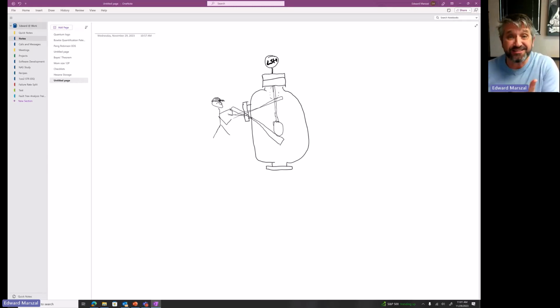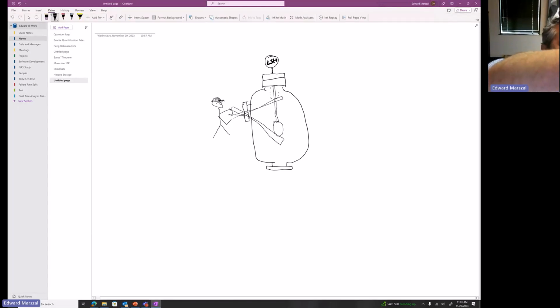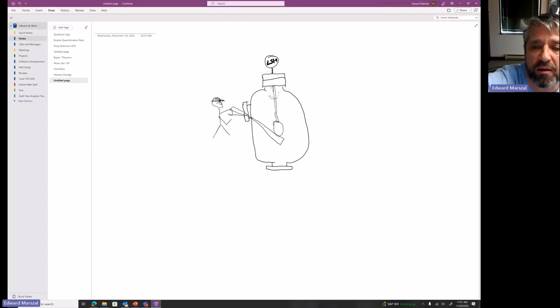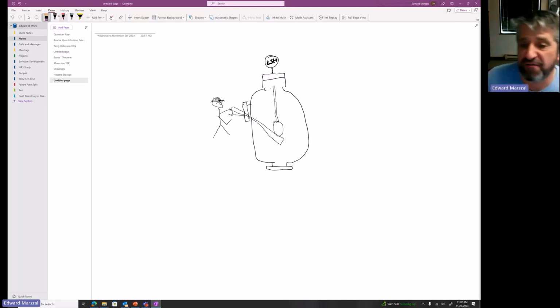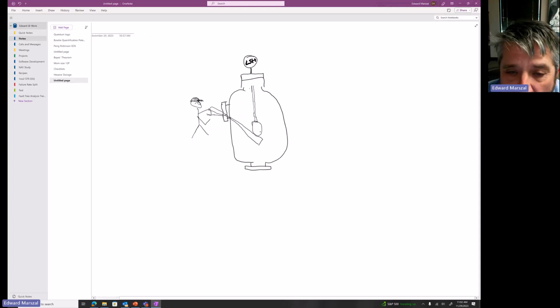Perfect test, yes? No, this is a very crappy test. So why is this a very crappy test? When you're writing your test plans, you need to think about what all the failure modes are. What are all the different ways that this device can fail? One of the failure modes that I know for sure exists with a float is a hole.